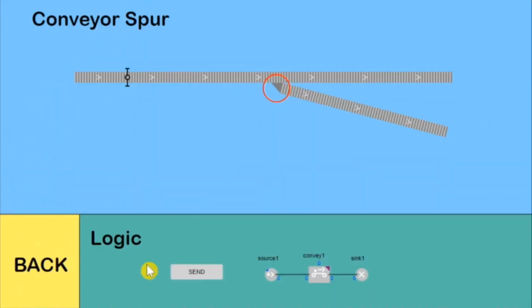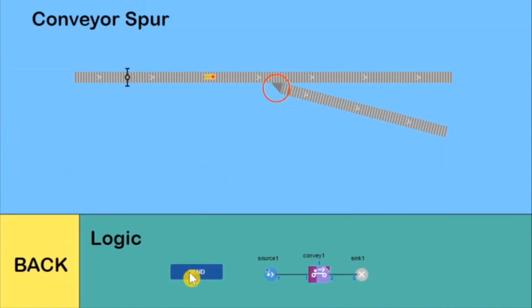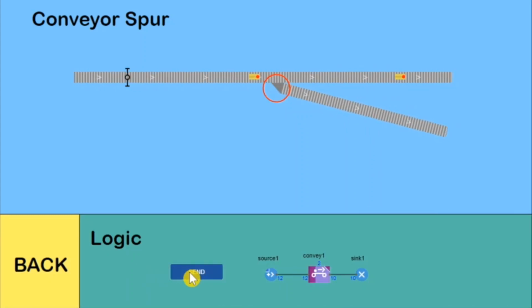Conveyor spur. Conveyor spur is the space markup element that is used to define a junction between a branch conveyor and the main conveyor. Agents passing through it keep their current orientation on the conveyor. The transfer of material items from the branch conveyor onto the main conveyor is automatically calculated so that it does not affect the normal operation of the main conveyor. If necessary, the material item on the branch conveyor will be delayed until the flows of both conveyors can be safely merged. The merge is executed at the maximum speed of the main conveyor.